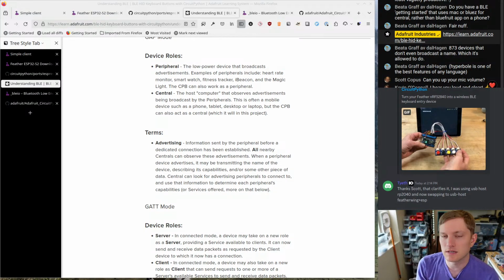Because BLE is very much designed for the idea that at any point, my devices are going to walk away from each other and they can't talk, or something's going to happen so they can't talk, and I need to reestablish that connection. So bonding is the process of basically saving the information for pairing. If you didn't save it, then you would have to do the pairing process every time. So that is how you discover BLE devices and how you could get them connected.